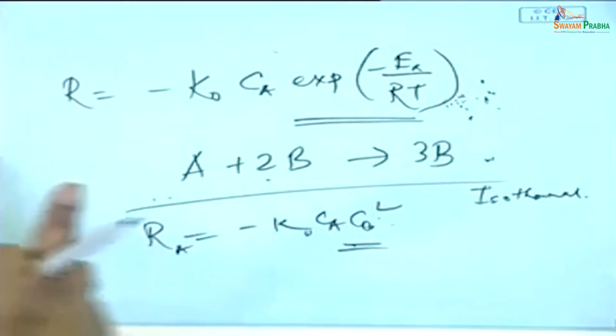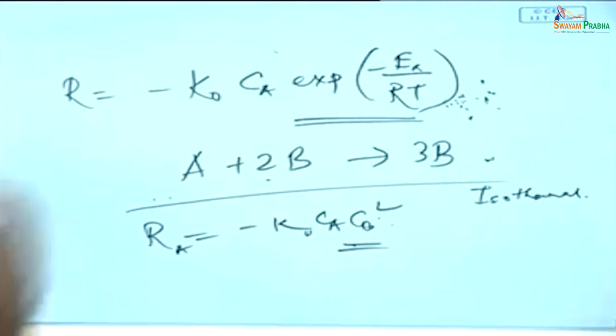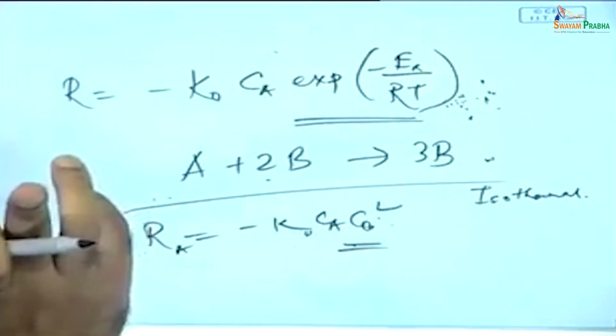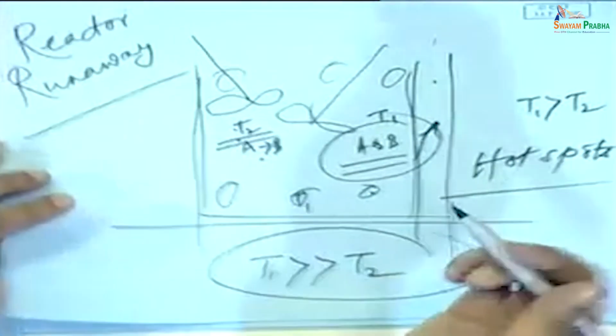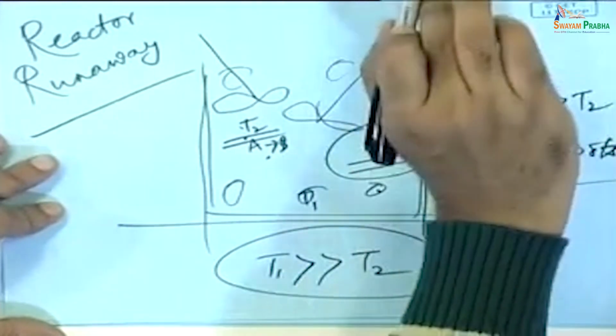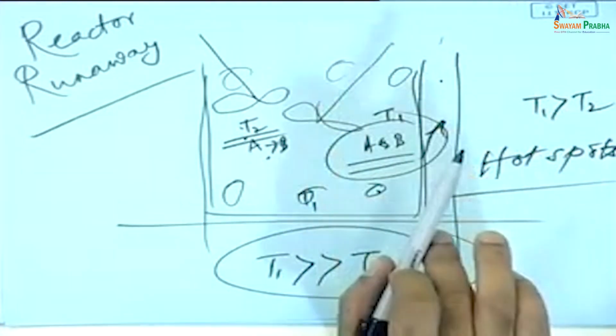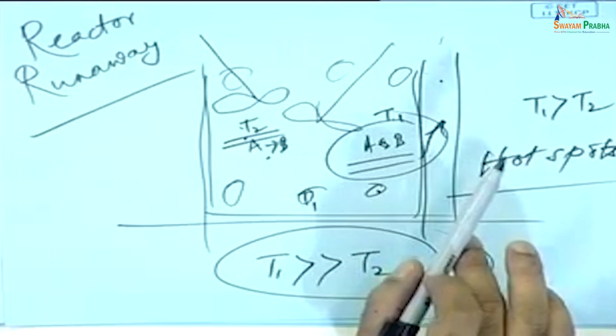So at the same point of time there could be two temperatures in space, or two values of a certain constant substrate or a certain product in space within a continuously stirred tank reactor. That is multiplicity, and because multiplicity is allowed, this is allowed to happen, right? Otherwise, unless multiplicity is allowed, the temperature in one spot cannot go up while the temperature in another spot remains the same. Is it clear?